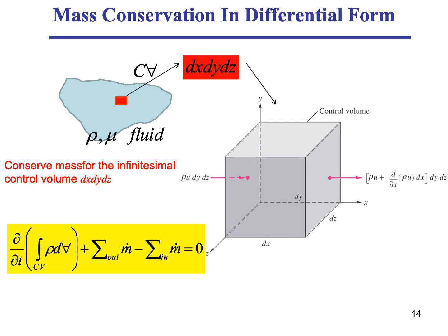at x, so this was at location x. I can predict it at location x plus dx, to be the value of rho u at x, which is this guy, plus the slope of rho u with respect to x multiplied by dx. Go back to the previous slide, and that's the equation in red that we had written over there.